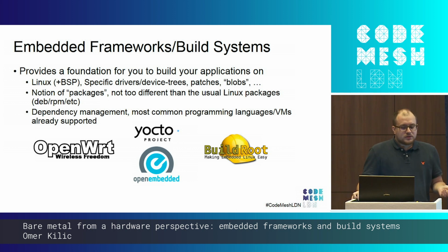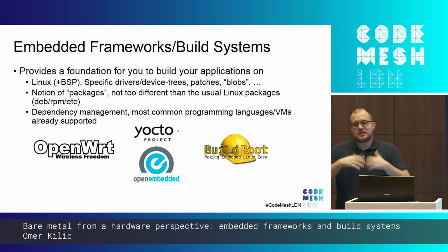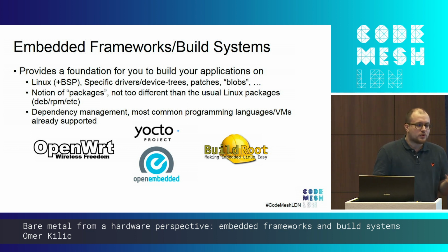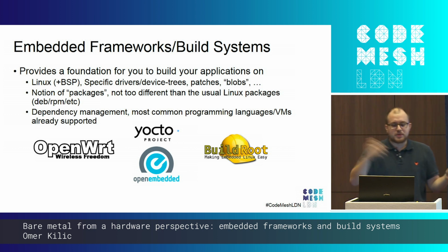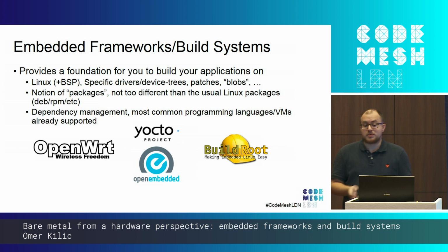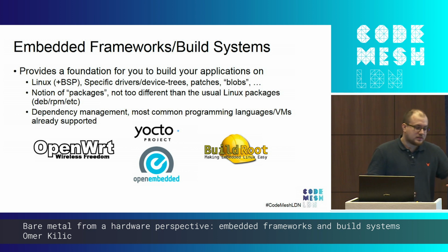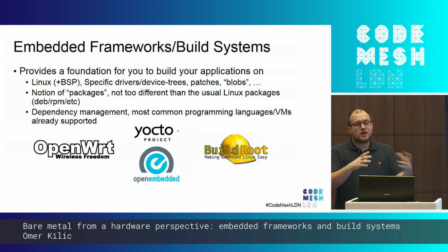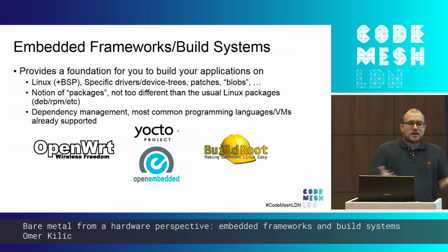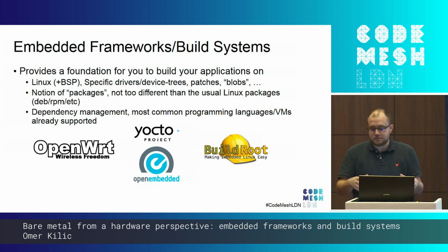They provide you with a foundation, or a base layer, that you can build on top of. It's not too dissimilar to the notion of installing a lightweight Debian installation, grabbing a few packages, and, if need be, packaging your applications and so on. But generally, these go one step below that, and they provide BSPs, board support packages, which take care of initializing the custom hardware that you have, which you don't generally have to worry about when you're deploying things on small Intel NUCs, or when you're running things on your laptop and so on.